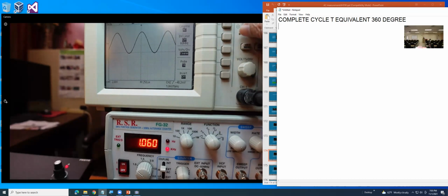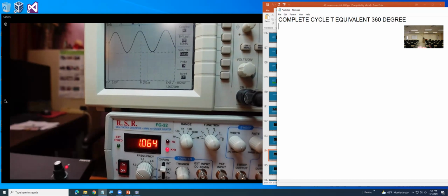Okay, now that one here, and we want to move it left or right, it doesn't matter. I'm asking you for this signal here, one complete cycle, how many divisions? 1, 2, 3, 4. Say 4. 1, 2, 3, 3.8. Okay, well, you're there, we're here. We can't see it as sharp as you can, but it's close to 4. Okay, let's see. 4. Okay, all right. Change the time base.